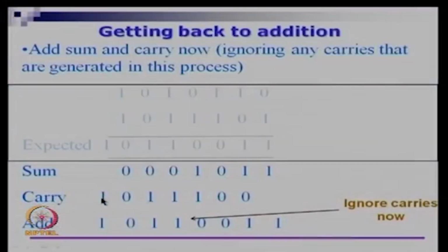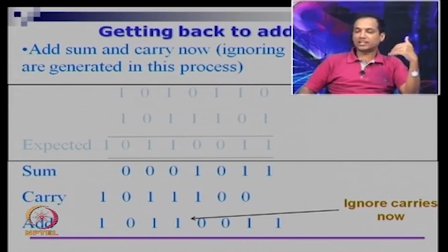At the end you will only have G's and K's. Take the G's and K's, interpret them as 1 and 0 respectively. That will give you a carry vector. The sum vector was available in the first step itself, and we took log n steps to get the carry vector. Take the sum vector and carry vector with appropriate shifting and XOR it together,